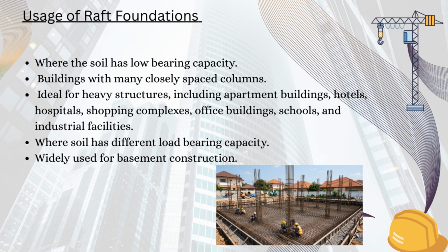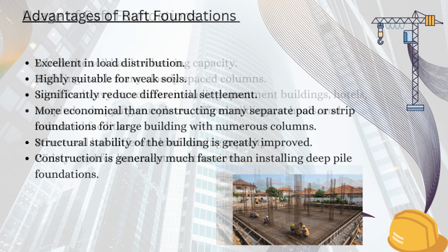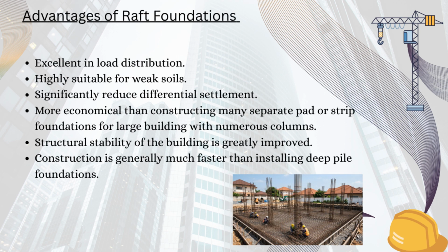They are also widely used for basement construction. In many modern buildings, the raft foundation also serves as the basement floor slab, reducing construction time and eliminating the need for separate footings beneath the basement. Now let's look at some of the major advantages.